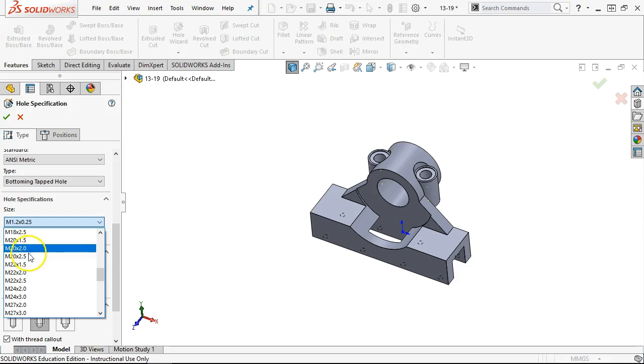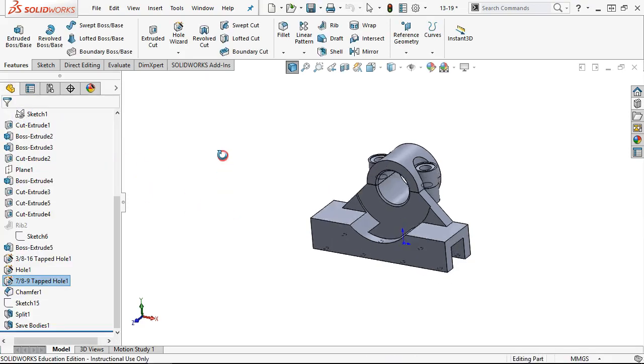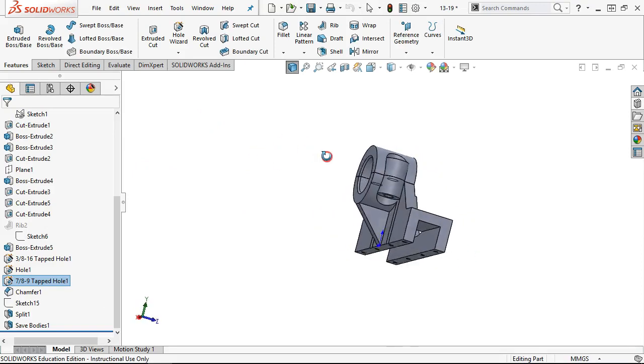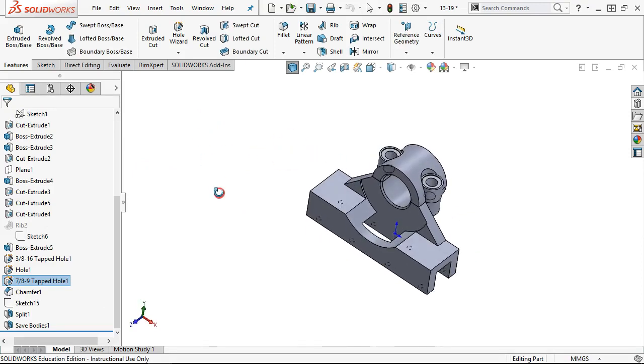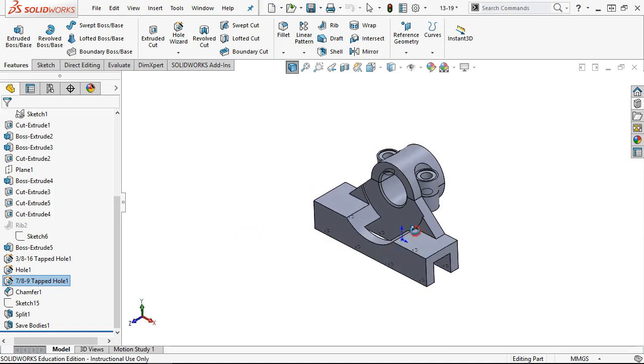20 is going to be .787, and that's going to be up at, if we just did 90, that would be 30. So we're a little bit undersized, but I think that's going to be our best bet if we're going to switch them over. Of course, the 3/8 would go to an M10 by whatever form we want to pick. So, it's not really that big of a deal. It's just what makes sense in those conversions.